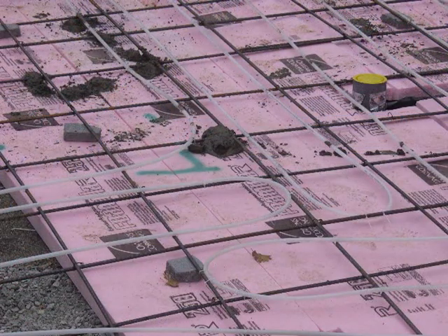And once you've done that, the basic premise is to take the radiant tubing and lay it out in the field and attach it to the grid of the rebar. Now, if you don't use rebar, if you use a welded wire mesh or some other kind of reinforcement, there are other ways that you can set the tubes in place. They actually make little stands that you can put right onto the insulation or onto the sub-slab surface that will hold the tubing in place as well. If you're using rebar, that's pretty much the easiest way to do it,